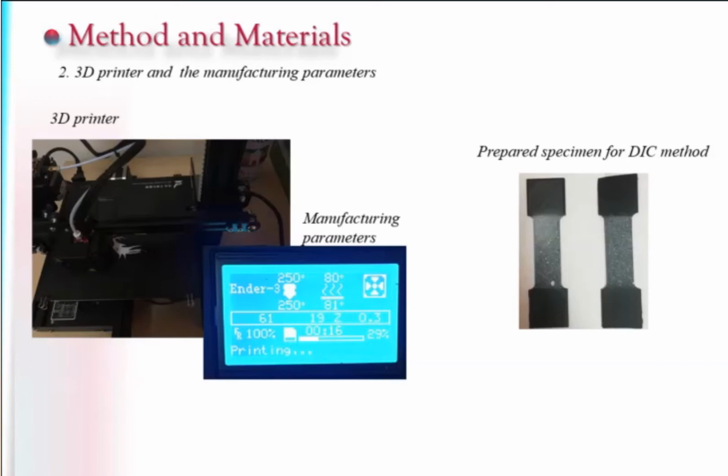During printing, the material takes the form of filaments which are unwound from a coil and fed through an extrusion nozzle. The nozzle melts the filaments and extrudes them onto a build platform. The measurement of displacement and deformation using the DIC system requires the preparation of the surface of an analyzed specimen.